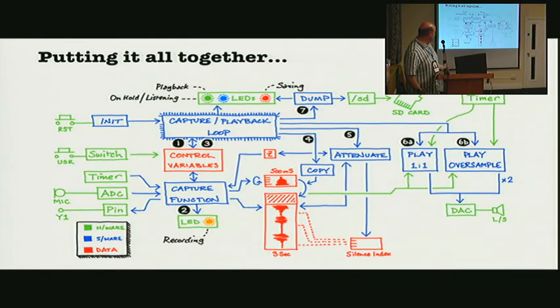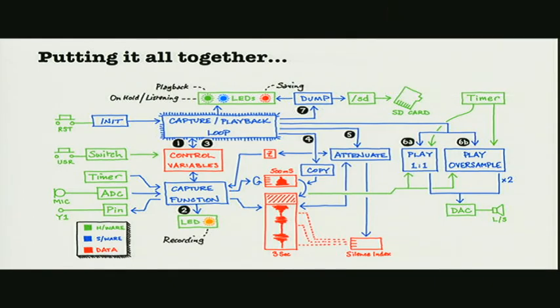Putting it all together is a block diagram here, where I have my recording timer that is triggering my capture function, which is continuously listening to this small speech buffer and then switching to the main speech buffer when it hears me speak. Then control variables switch to the attenuation algorithm, which erases areas of silence, and then I have a playback function which just writes to the DAC.